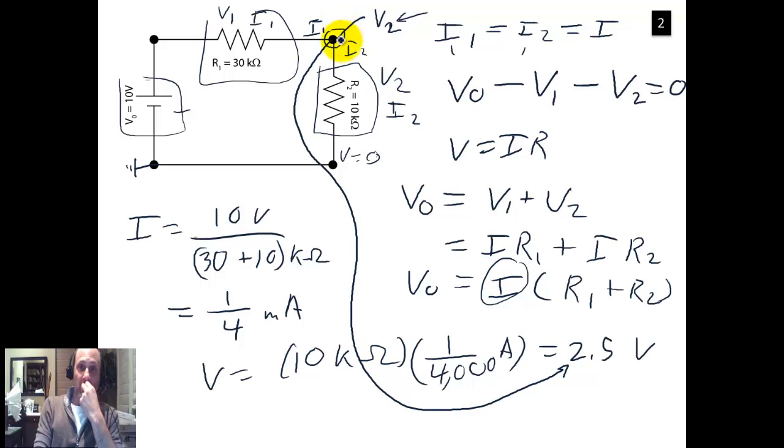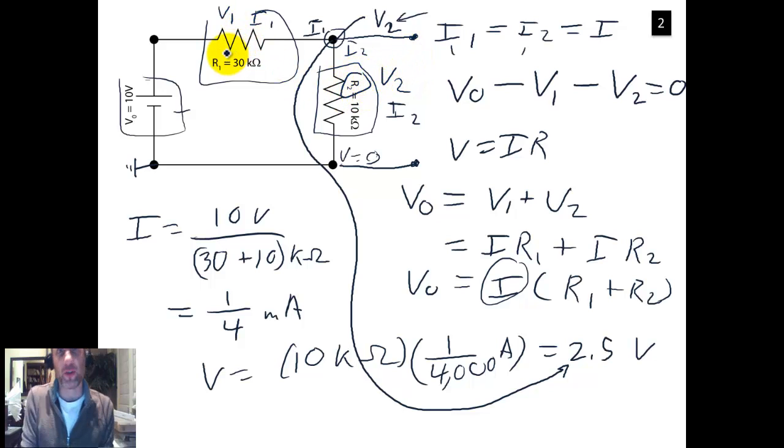So if we wanted to change this and alter the voltage that we have here and use that voltage for something else, and this is something that you're going to be doing in your homework, you might want to use it to power an LED or something like that, or in your case power the spectrophotometer. You just have to toy with these resistances, these R1 and R2.